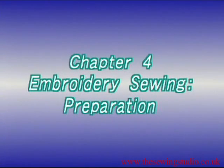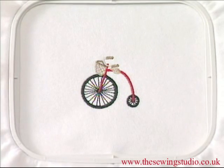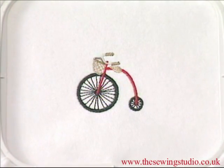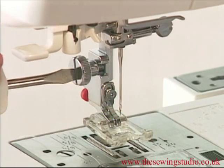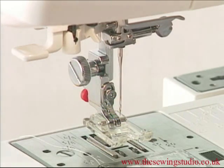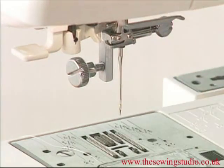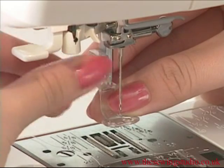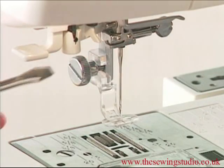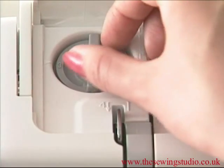Chapter 4. Embroidery Sewing. Preparation. First, it is necessary to change the foot. Turn off the power switch. Loosen the thumb screw and remove the foot holder. Attach the embroidery foot P on the presser bar from behind and tighten the thumb screw to secure the foot. Reduce the foot pressure to 2.